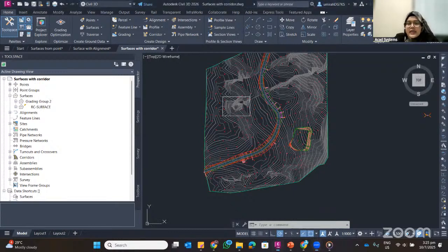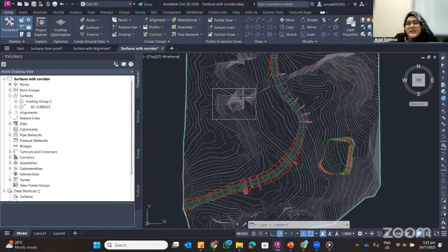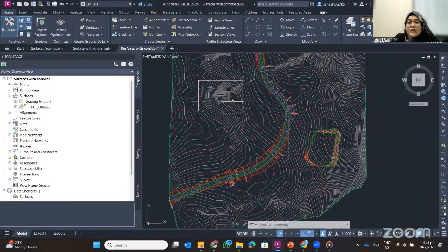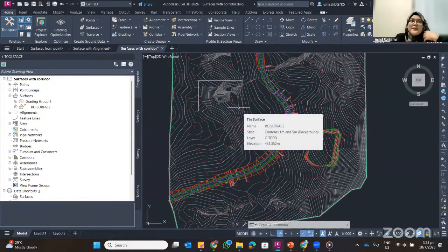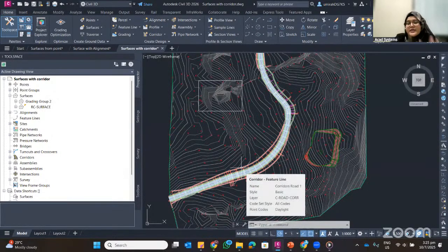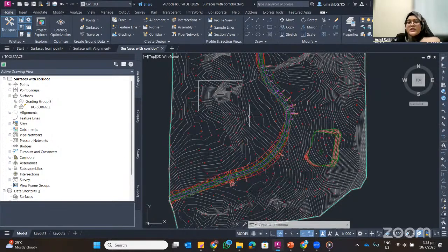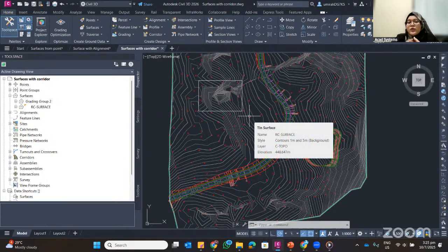So from here, let's say I already created the area here. Oh, sorry, I want to add the break line first. Okay, break line is a feature in surface in Civil 3D, which is where you want to add a contouring line to your existing contouring. Let's say you create one more line, and then you want to make sure that line connects to the existing surface.